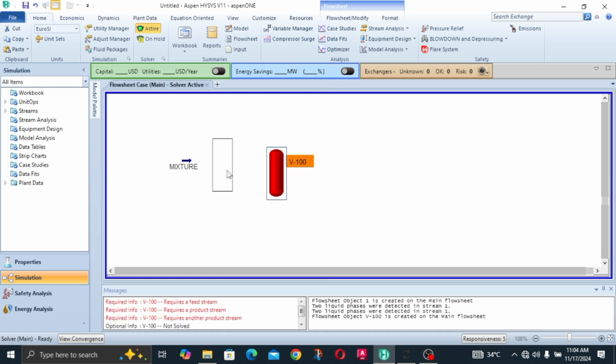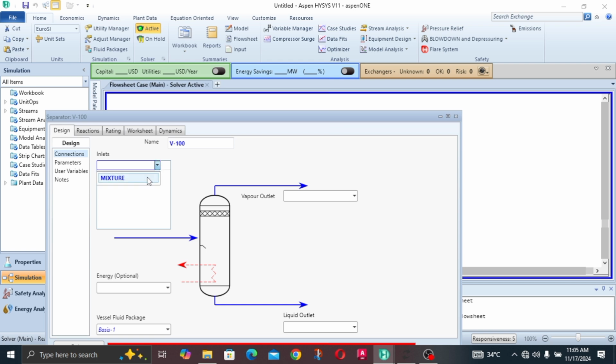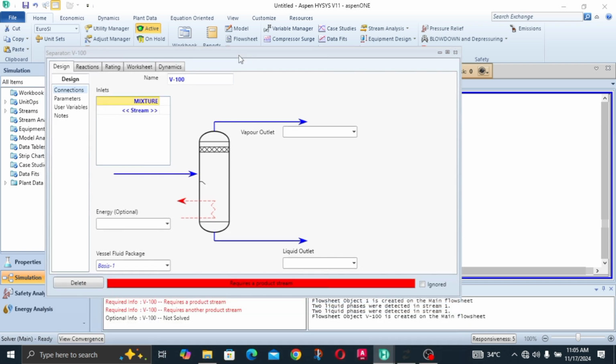That's the 9th equipment, traditional 2-phase separator. Remember, for the equipment, you connect your inlet and label your outlets. And the separator is no different from the other equipment you have been handling. So this is the vapor outlet at the top, which signifies the gas outlet. Then we call this the liquid outlet, where the liquid would pass.